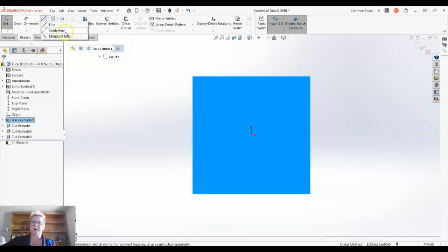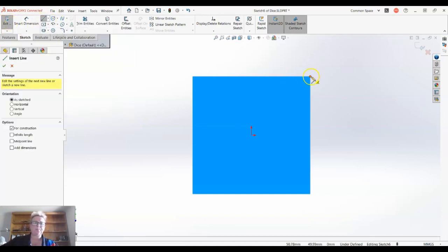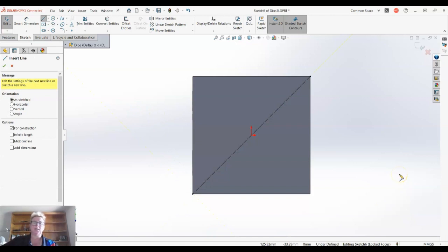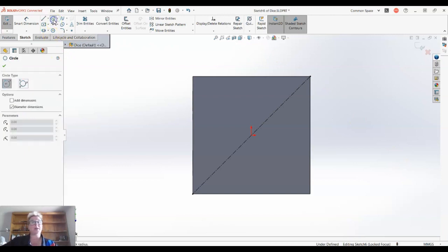So let's grab our center line tool, and it doesn't really matter whether you go there and down or there and there, either way. We're going to left click on that orange dot there, come straight through the center, down to the opposite corner and left click, and here it is still attached. I'm going to double click and it's gone, or press escape on your keyboard.